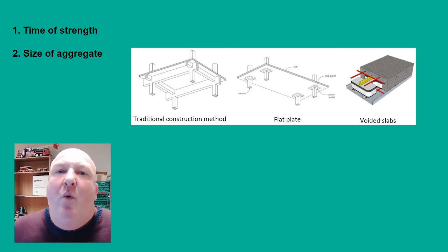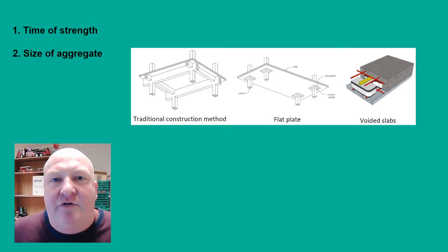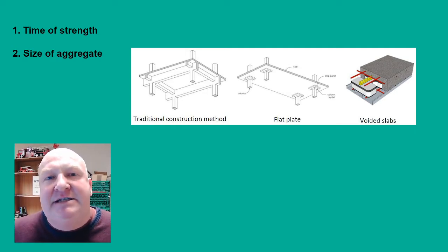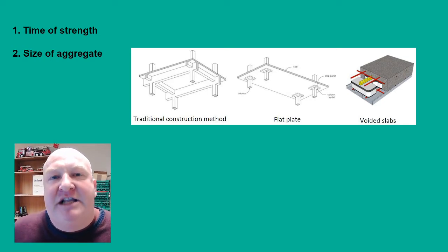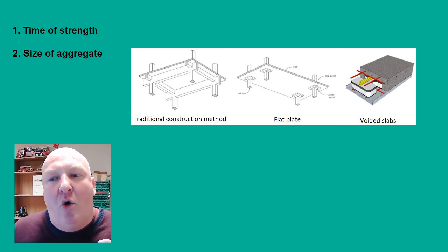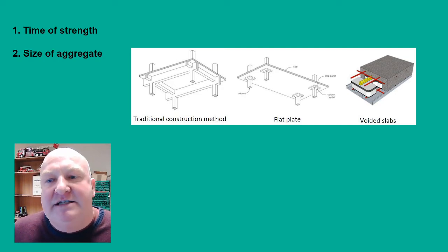What will that be? Well, as you all well know, in the middle of the construction, where the neutral axis is, we don't need that much material to carry the load, because there is no load there. So what voided slabs are is that we are making boxes or anything to have voided rooms with nothing inside in the middle of the slabs, to take away that concrete that is not needed. So we get a whole room with air instead of concrete, where the concrete is not needed.